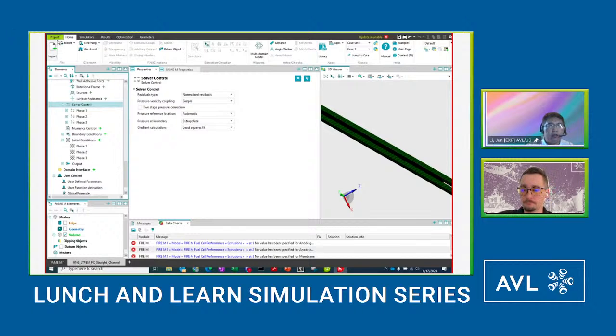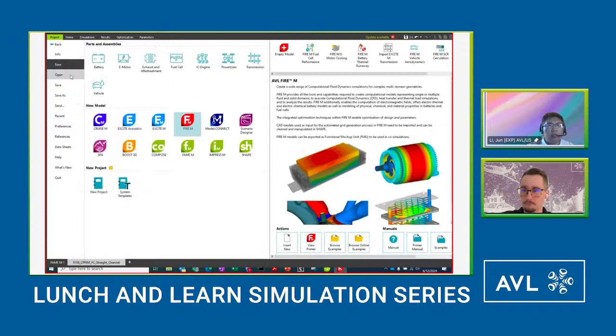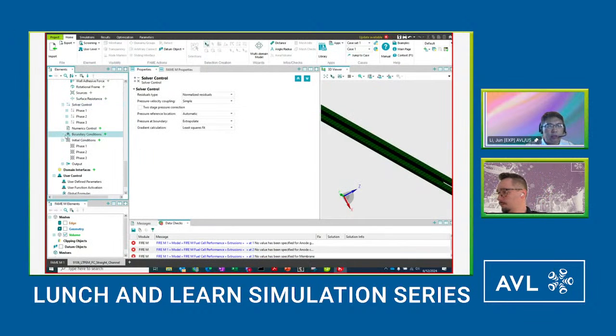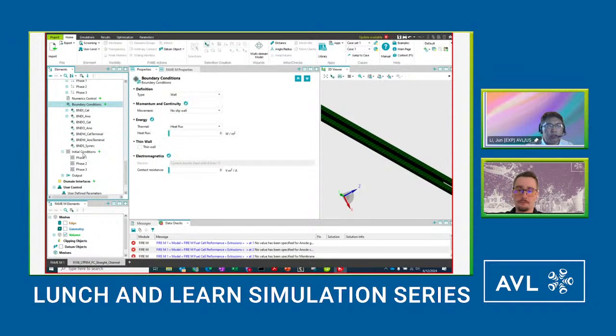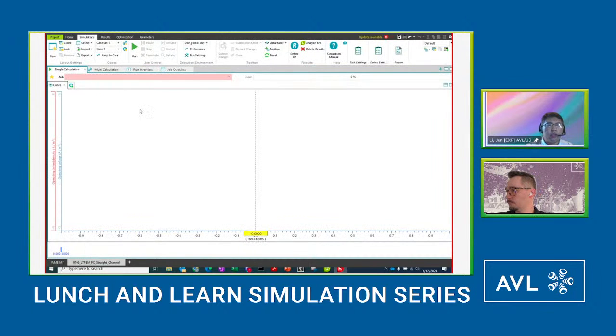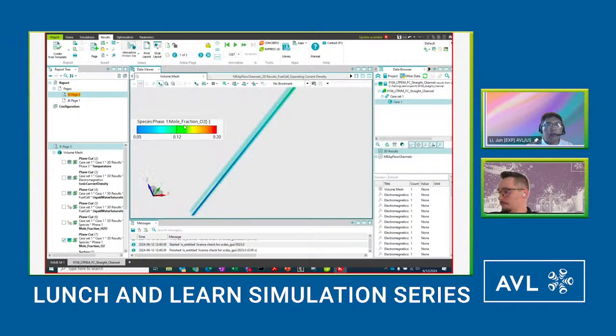So basically everything you can set based on some template. For example, we have this fuel cell performance template. You can use it to set this simulation up. And then we specify the boundary conditions and then the initial conditions. Basically, that's what you need for this case. And then you can start the simulation and monitor what's going on during the simulation process. And after the simulation is done, you can look at the results.